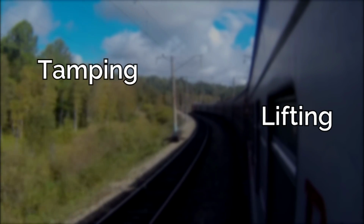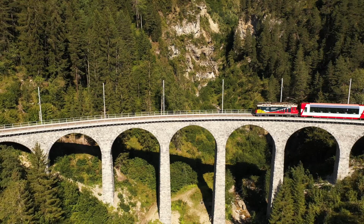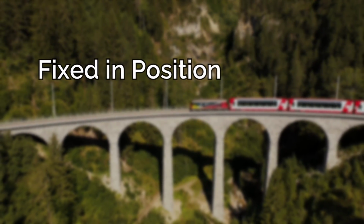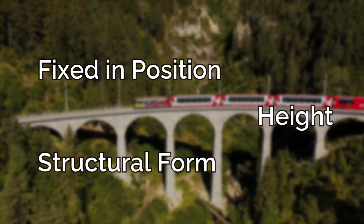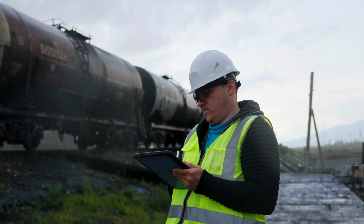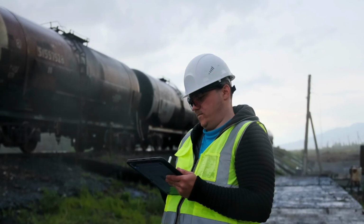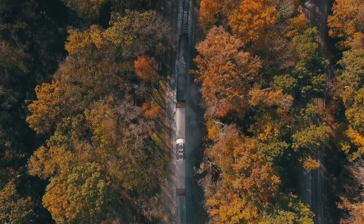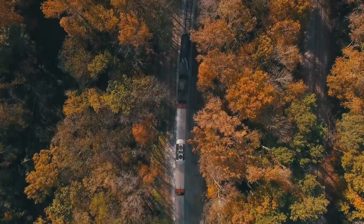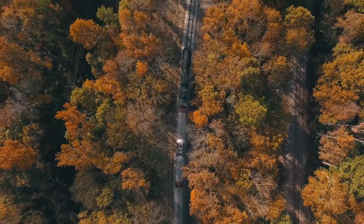Track typically sits on ballast. Its position can be managed by tamping, lifting, and slewing. Because of this flexibility, it's considered to be floating. Bridges are different. They have a fixed position, height, and structural form. You can't shift them sideways, raise them easily, or adjust their support conditions. Once built, their location and design can't be adjusted like the rest of the track. Just think of the work needed to demolish and move a bridge. It means you need to think differently when you approach them, because things start to get difficult.